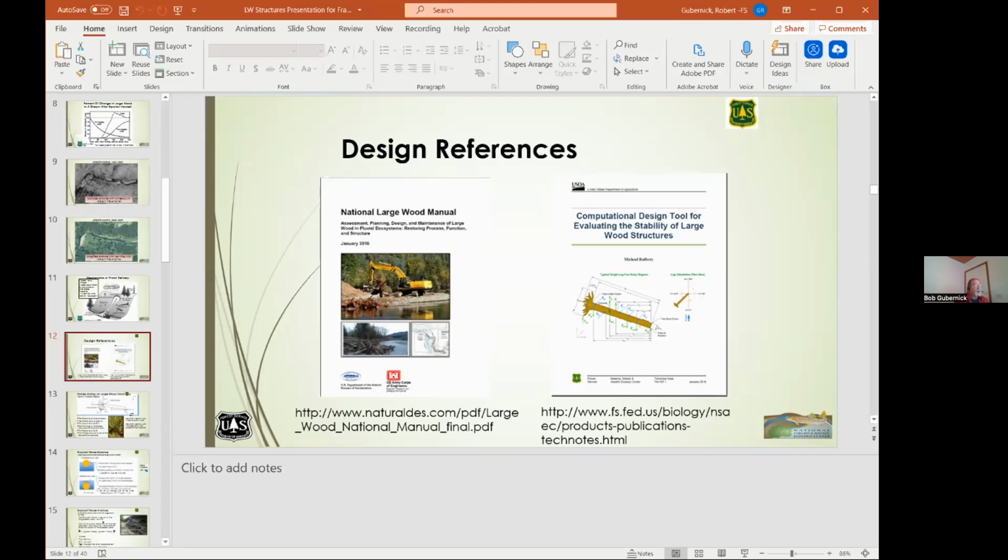It depends upon the scale. The wood with root fans, the reason why they're so good is that if you look at a weight distribution in a log, that root fan, the first 5 or so feet of root fan and stem is as heavy as the next 30 to 40 plus feet. And then also the root fan has a claw. So if it breaks away, it doesn't go very far. You can use logs. They just make things a little more difficult.